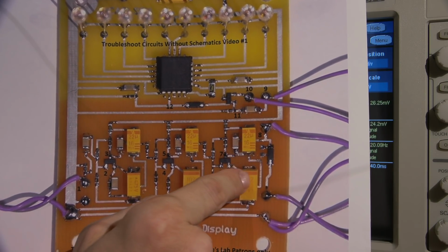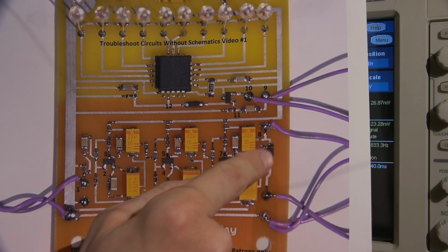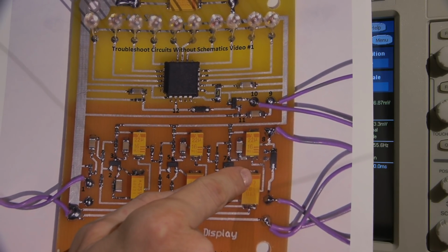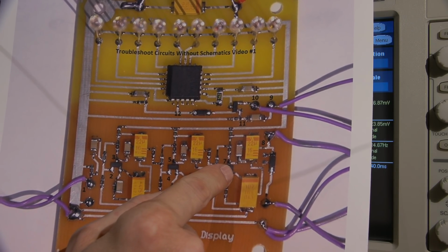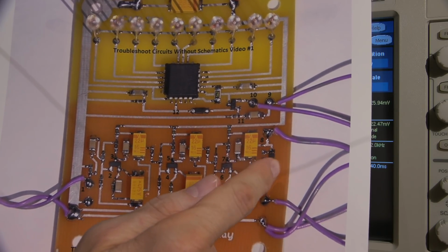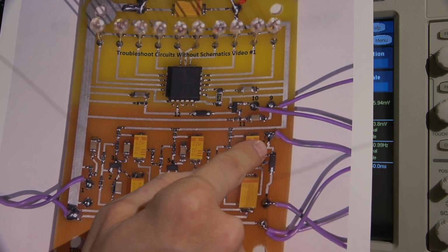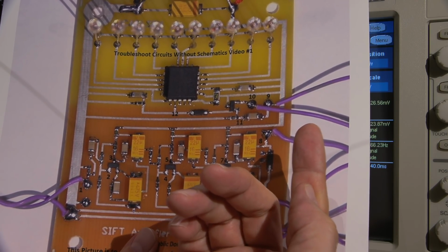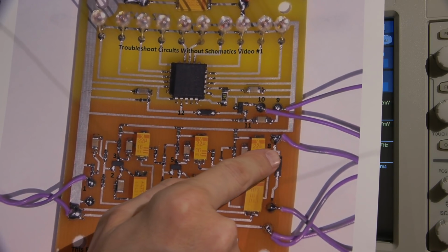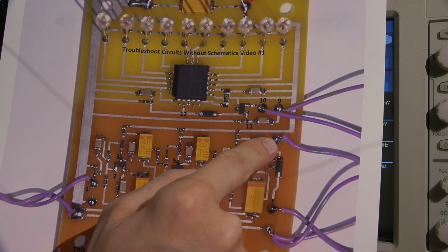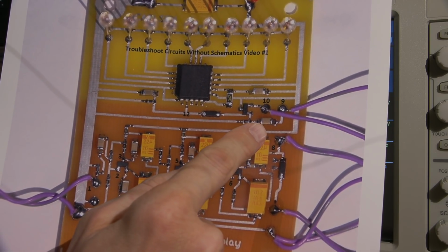Well, first of all, just through recognition, whenever you see a small rectangular black block on a board like this that only has 2 leads on it, there's a really good chance that it's a diode. Now, if it is a diode, we don't know what type of diode this is. It could be, because we don't know what the circuit is and what's going on, a Zener diode? A Schottky diode? A standard diode? We really want to find out what this thing is. We also want to find out which way this is installed in the circuit. So that's what we're going to do now with a simple diode test.